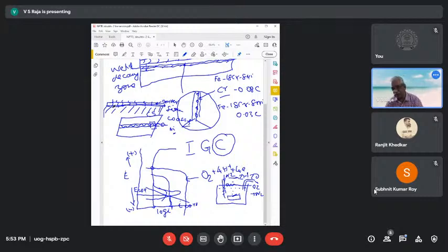And there's one more similar thing called plasma electrolytic oxidation or micro arc oxidation. That gives you thick oxide coatings. That also gives you better performance because they're all thick coatings. But generally, normal conversion coatings are not good, so they won't give you a longer life actually. Okay, I hope that point is clear to you. If you still have any questions persisting, please do type in your question so that I can answer you.